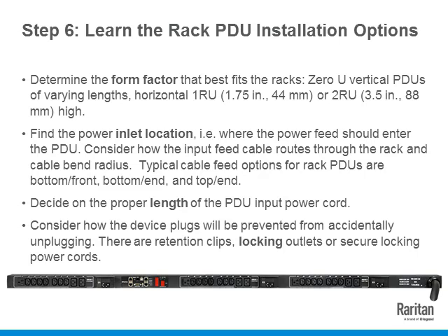How about the power cord length? How does that matter? We have all seen this when we lift up the raised floor. There's a big nest of cables, which could be completely avoided if you can customize the length of the power cord that you need for the rack. Or even in an overhead busway application, it's the same kind of idea where we've seen plenty of instances where these power cords are coiled and just literally sitting on top of these racks, which could be completely avoided by just customizing the length of these power cords.